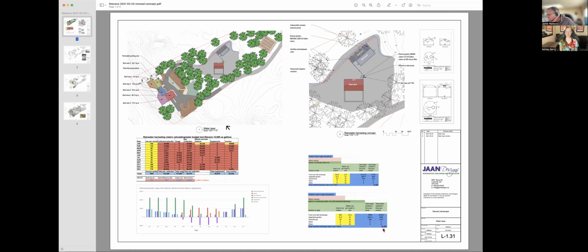So in this situation, outdoor water usage is in and around 31,000 liters, so that's probably 8,000 gallons a month. We can't collect and store everything we need. We're still overflowing, redirecting about 55,000 liters. Even if we could store everything we needed, we wouldn't quite meet the needs for the site off of this one roof. We'd have to look elsewhere, and that could have been done by looking at these other roof surfaces. The client didn't want to do that.